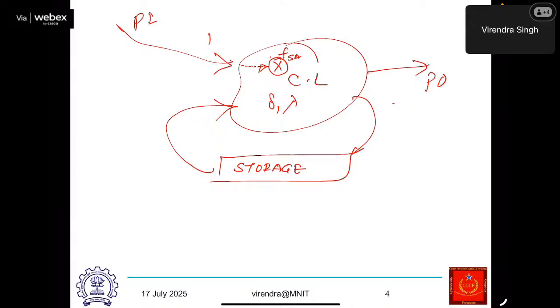But sometimes it is possible, sometimes it needs the help from the storage element, and if it needs help from the storage element, in that case I also need it from here, and I don't know what is stored in the storage element, so I have to assume x. If I assume x, perhaps this may or may not excite the fault.